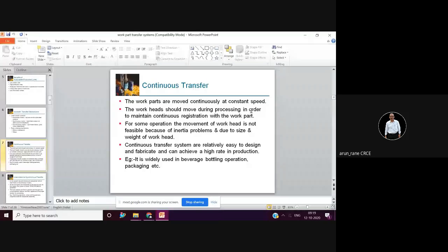Why? Because Volkswagen is top loaded, so it has many components, whereas in Bolero the components may be fewer. So the number of workstations required for the Bolero assembly line will be less as compared to the Volkswagen car. The number of workstations can be 10, or it can be 40, or even 60. It depends on the work content.